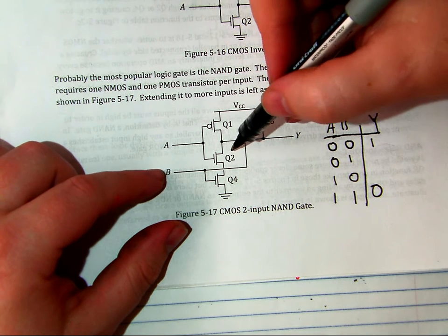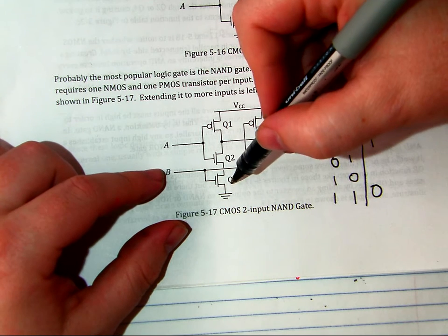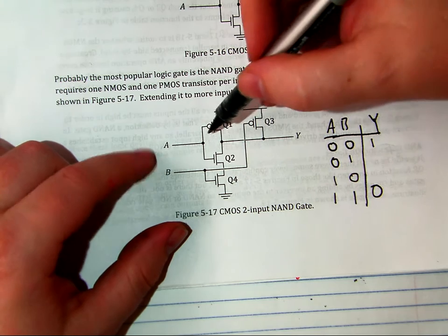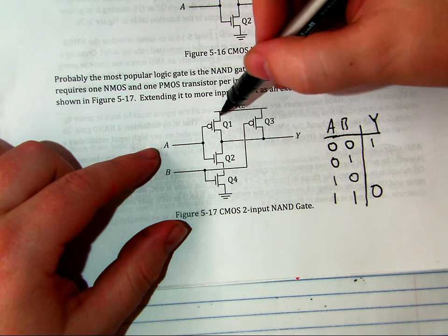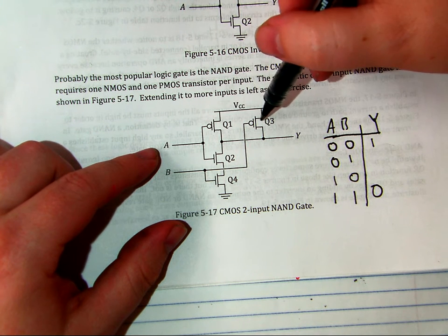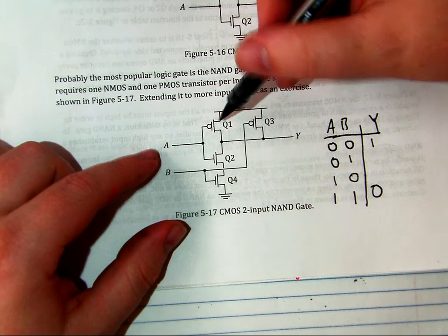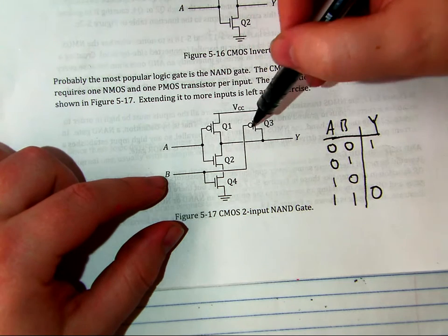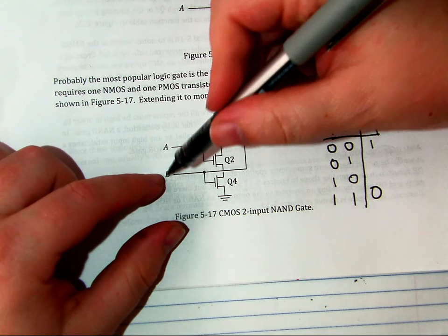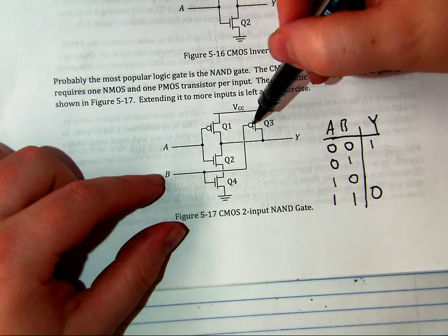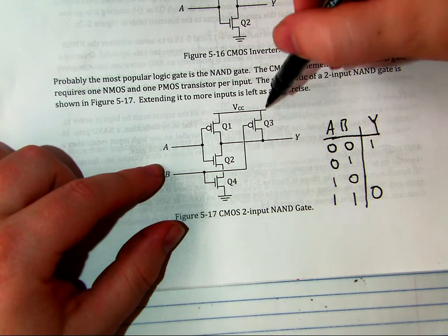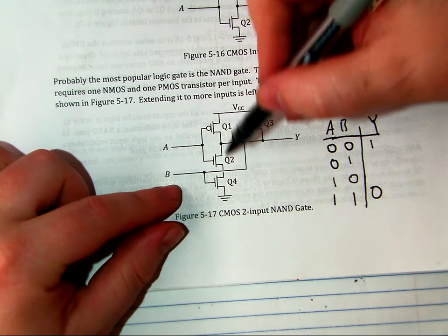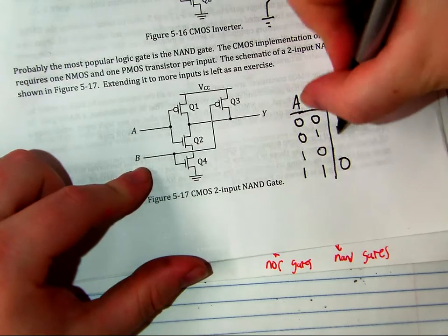What that means is it cannot be 0. Is it 1? Well, if A is 1, this is connected to VCC, so it actually doesn't matter what Q3 is doing if Q1 is connected. And similarly, if B is on, rather 0, right? So 0 means this is connected, then this is pulling to VCC. So as long as either one of them is 0, they're connected to VCC, and they cannot be connected to ground, which means we get 1, 1.